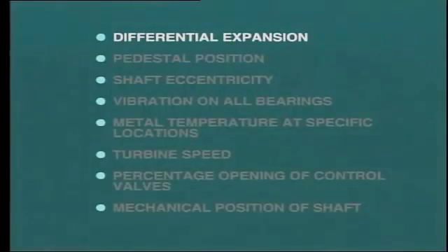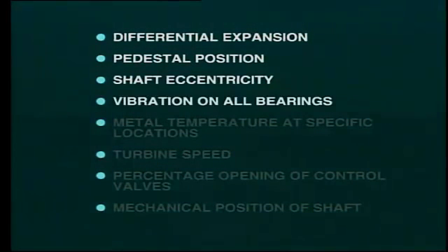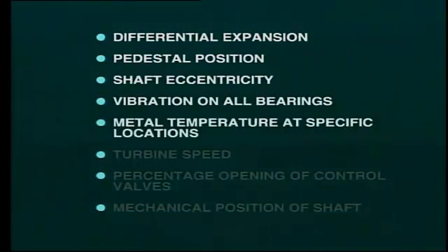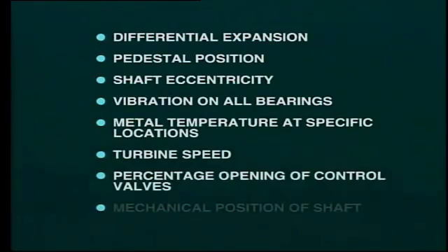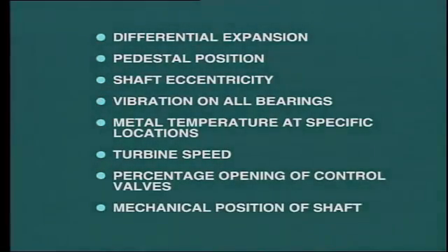Commonly, this includes the following information: differential expansion, pedestal position, shaft eccentricity, vibration on all bearings, metal temperature at specific locations, turbine speed, percentage opening of control valves, and mechanical position of the shaft.